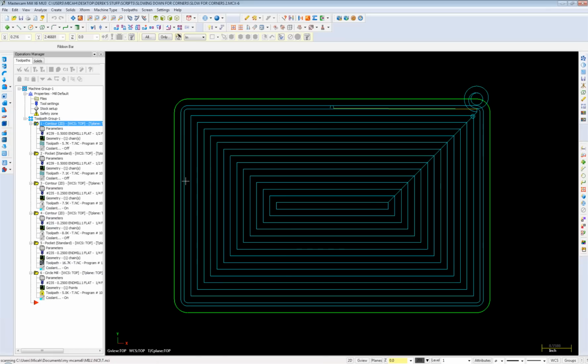Kurt is asking, where is the high feed rate switch again? Can you point that out one more time, Micah? Right there. So if you select the toolpath and then click the high feed, it'll apply high feed to that toolpath. Try not to click the stick of dynamite instead, because that will not have the same result. Well, it asks you first. You can click yes. Don't delete everything. No, that's not what we want to do. Okay, so Jimmy's going to switch from 1 to 1 filtering to 2 to 1.